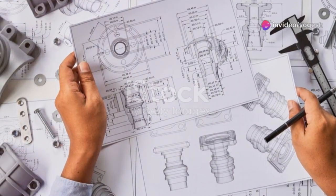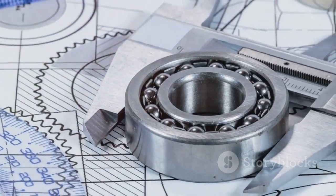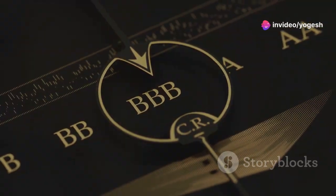How do we show concentricity on a blueprint? With its own GD&T symbol, two circles, one inside the other, a bullseye. This symbol appears in a feature control frame, a rectangular box with three compartments. The first compartment shows the concentricity symbol, telling you what's being controlled.